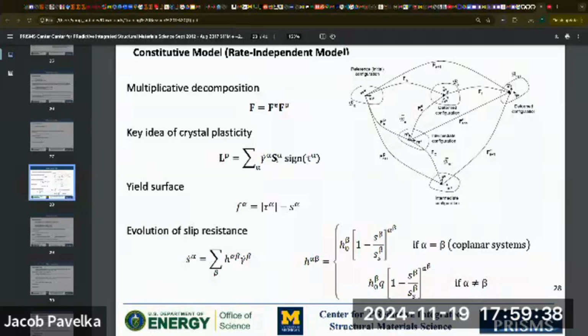As I said previously, these elastoplastic materials have an elastic part and a plastic part. Is this S the Schmid tensor? Yeah, the Schmid tensor. Basically, crystal materials have different planes that might shift relative to each other. That's what we call plasticity: sub-plane dislocation motion and all these things.